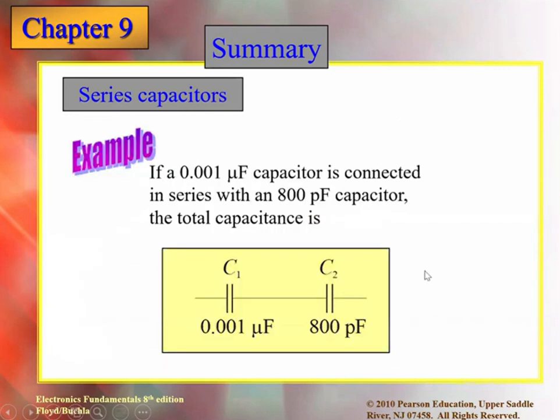So see now, based on that, it's so simple. This is C1, C2. They are connected here, you can see they are in series, one end to another one. So I need to find their series combination. You can see their units are different. We need to have the same unit, then we can put it in. So you can write micro 10 to the power minus 6, pico 10 to the power minus 12. Is it 12 for the pico?